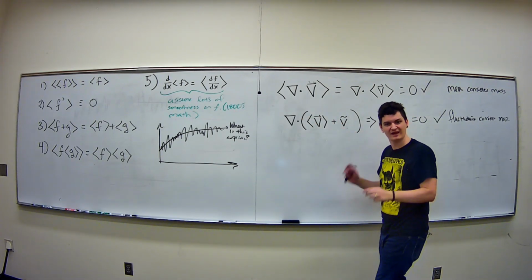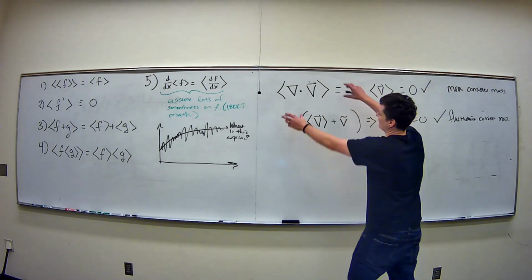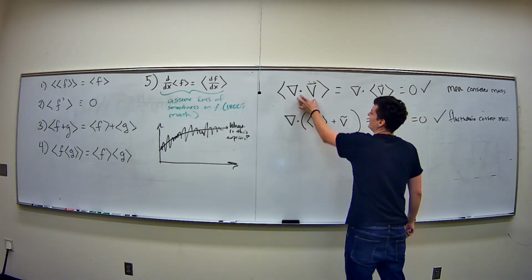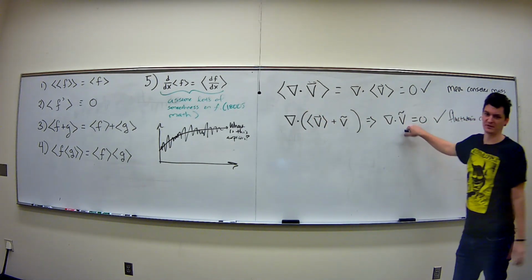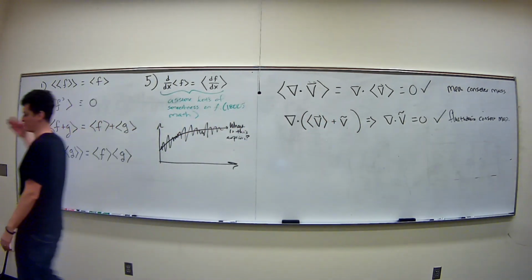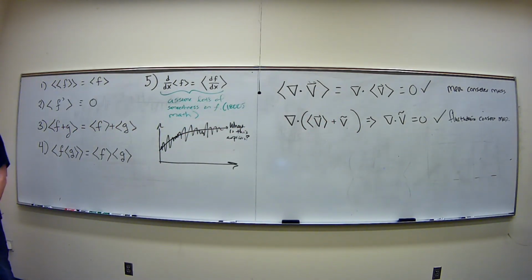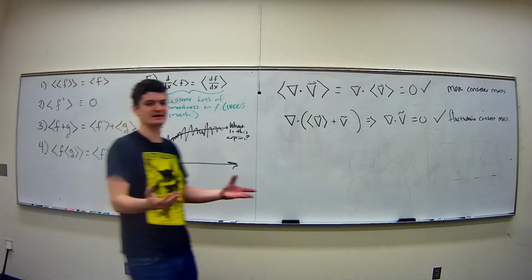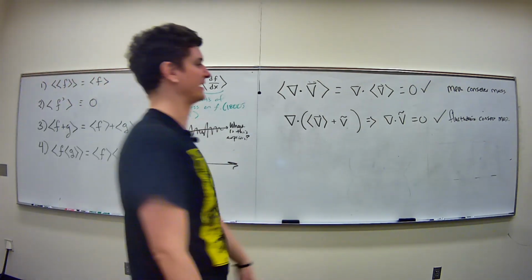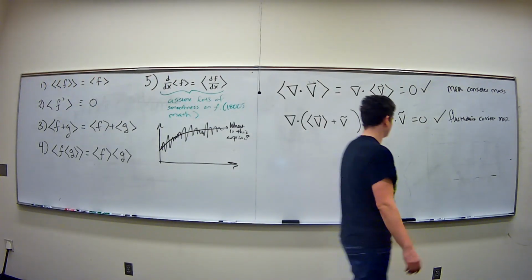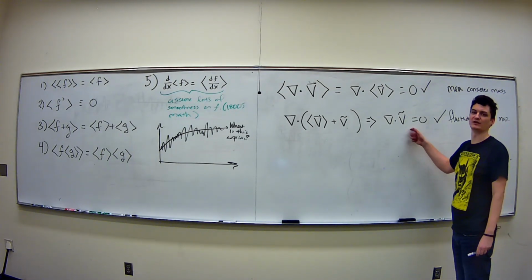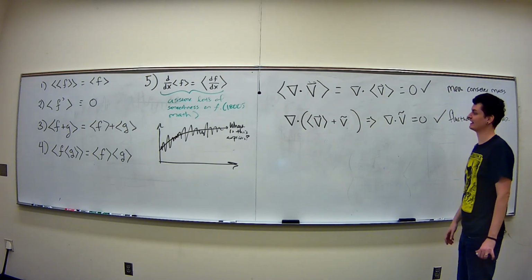Do you see? Fundamentally, that's what I'm doing right now. This is the average, and this is my assumption of what the solution looked like. If you tie these two things together, you get that the fluctuations conserve mass, which is nice. You wouldn't want to model something and then have your fluctuations be able to create mass. It could be a model that might trick things to work, but that wouldn't make sense. So extra credit, I would say, is to dig into what's really wrong with your fluctuations conserving mass in a limiting sense.